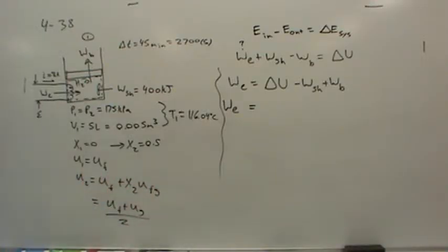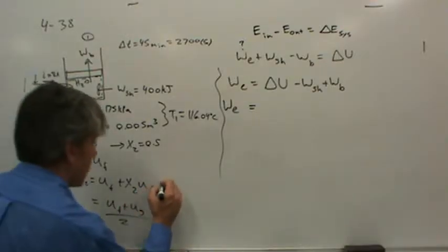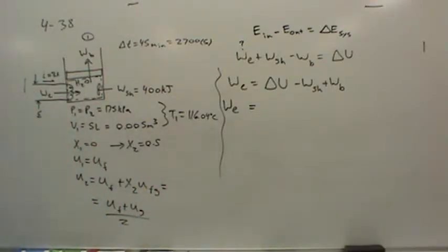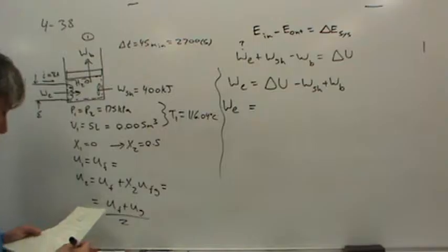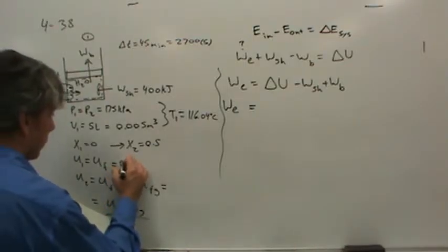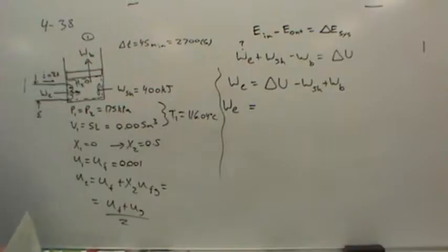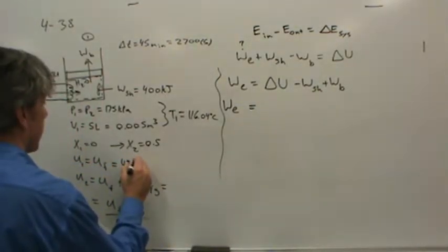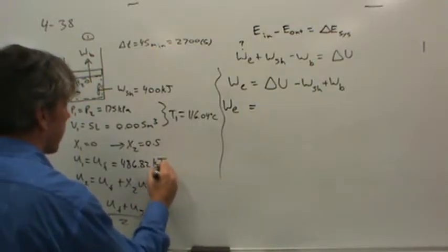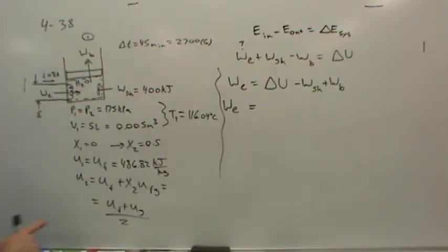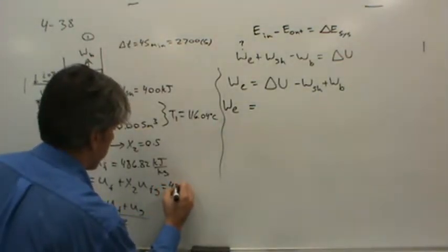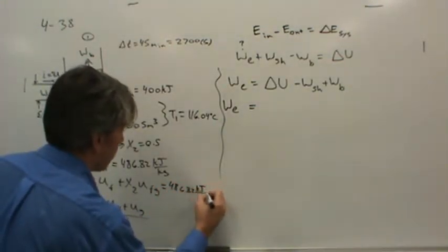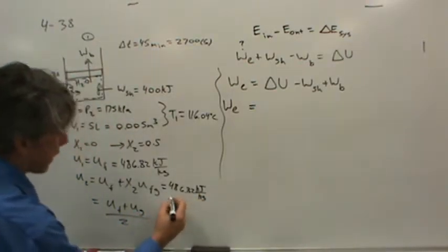Anyway, for our purposes, let's go ahead and calculate the internal energy in state 2, and let's read off the internal energy in state 1. So give me UF. 0.001057. Did you read off VF or UF? That sounds like VF. Yeah, UF is 486.82 kilojoules per kilogram, right? Yeah. Okay. So that's what goes in here for UF, 486.82 kilojoules per kilogram.